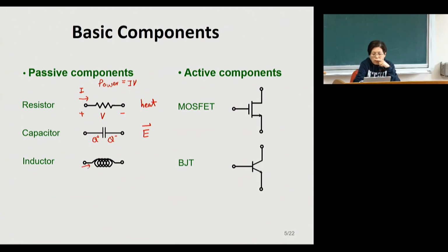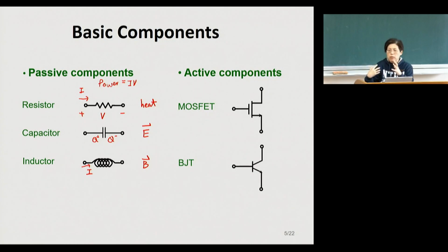In an inductor, when you inject a current, it is stored in the magnetic field. So your energy doesn't go away. If you're using an LC oscillator, it transfers from electric form into magnetic form, and then it oscillates. And if there are parasitic resistors, a little bit will be dissipated as heat.